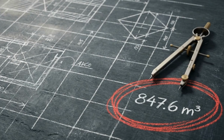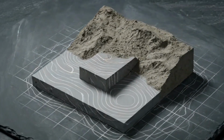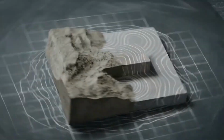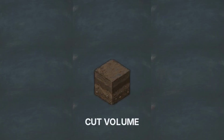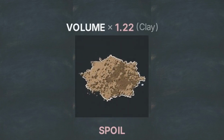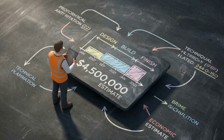We started with uneven, organic terrain. We mapped its slopes, established a rigid geometric grid, and processed spot heights to find our exact cubic volume. Before you make any phone calls, take that final number and multiply it by your soil's bulking factor. You have to account for expansion. With that adjusted volume in hand, you know precisely how many trucks to order and how long the excavation will take. You can price the job accurately.